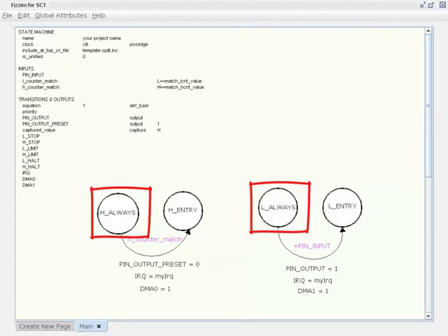In fact, this is a pseudo-state, which means it does not relate to a specific state of the state machine. It is just a shortcut to indicate that whatever transitions or actions are being linked to this state, these will have effect in any state of the state machine. It is just a graphical shortcut, so that you can avoid drawing the exact same event in all states of your state machine diagram, which could save you some time.